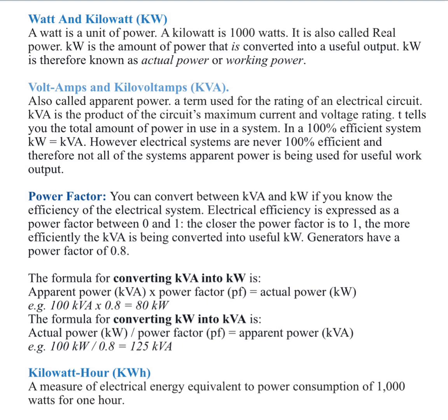For example, you can see an inverter rated 10 kVA or 20 kVA, but that doesn't mean that you can use the whole 10 kVA in that system. You will check for the power factor. Is the power factor 0.7? Is the power factor 0.8? Is the power factor 0.9 or 0.95?